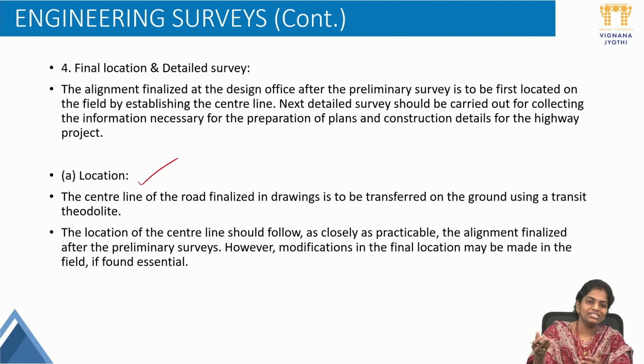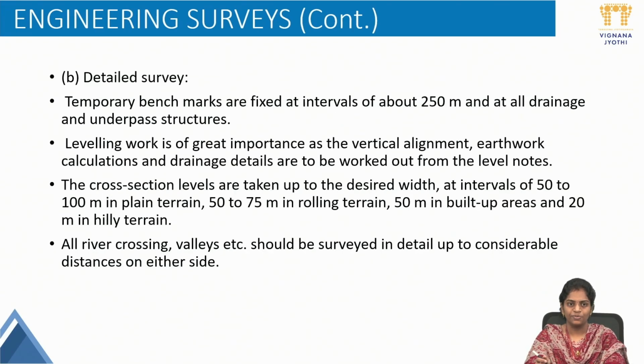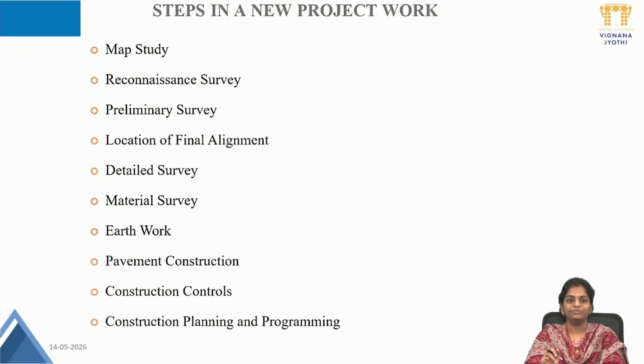That should be done using a transit or theodolite, whatever equipment we may use. Now we are practically using more advanced equipment to finalize the location. Next, detailed survey: temporary benchmarks, how leveling should be done, what the depth of excavation should be, all those details should be done.